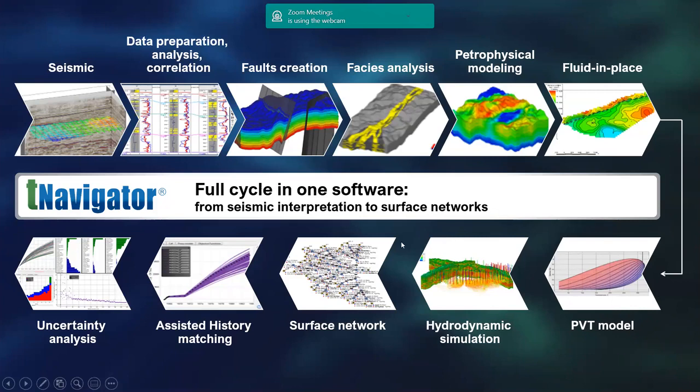Okay, and using your simulation, right here, you can either control your well with some BHP or THP, meaning that you have to specify your VLPs, so vertical lift curves. So here actually there is something missing, we have the VLP tool also.